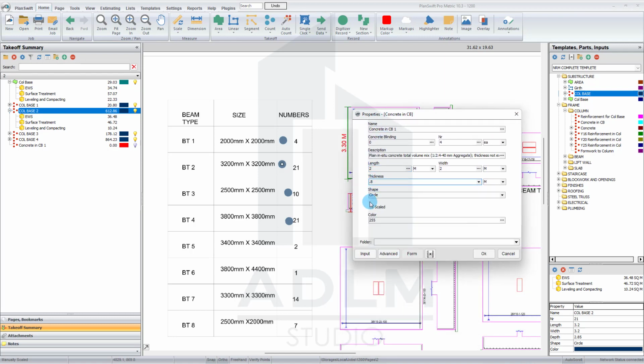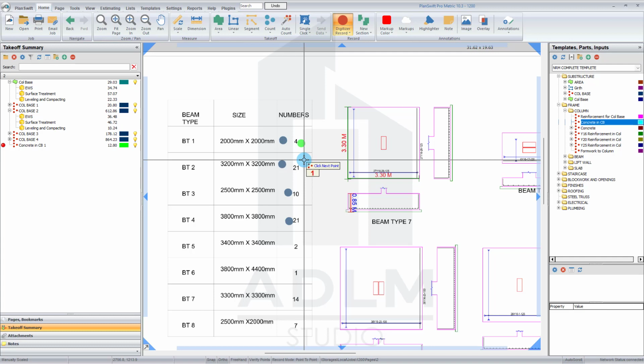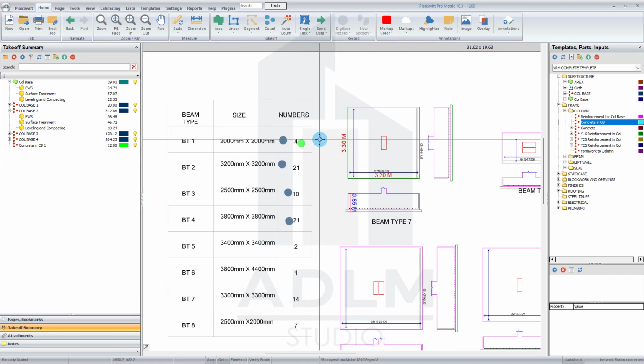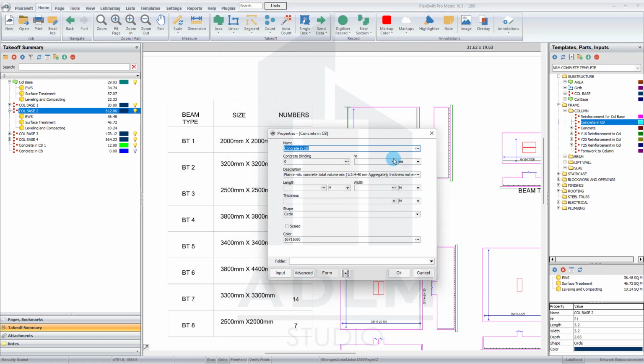Now once you've done this at 0.8, leave all of this, just click OK and identify that you just picked for this first one alone. That's this blue mark here. That's for the concrete in column base. Now stop. Once you're done with this, you pick the next one, which is column base 2. Just pick this, just turn it on. It's just a single click.